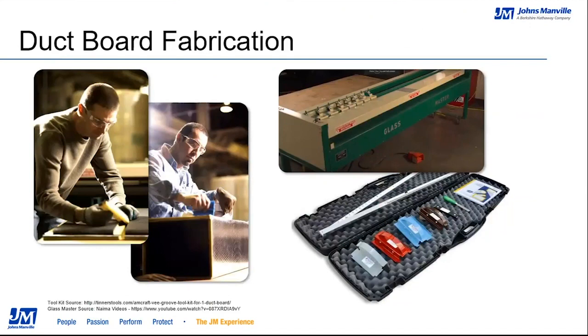In addition, ductboard can be fabricated using specially designed hand tools or via a ductboard grooving machine to create an actual duct, which there's some pictures of here on this slide. The top right is essentially a Glassmaster machine that you would use to groove ductboard. If you're a contractor using a lot of ductboard for projects, that's more than likely something you're going to see either at their shop or at a local supply house that's being offered to contractors to use.